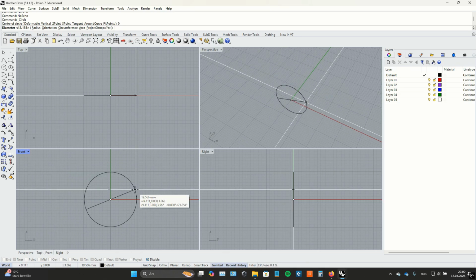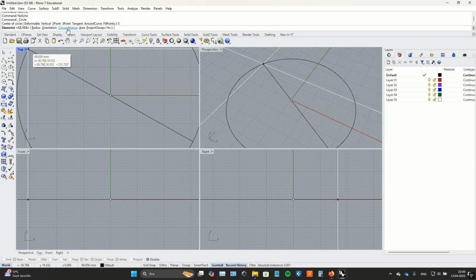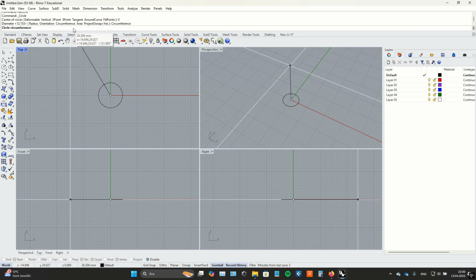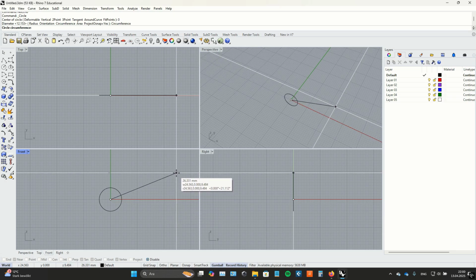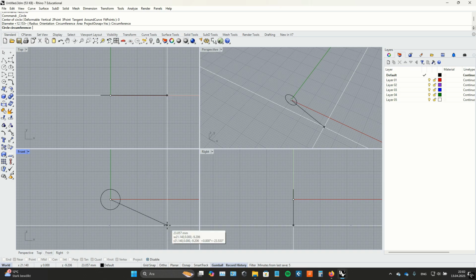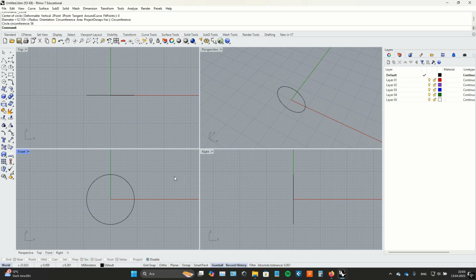I don't click anything just yet, just coming up here and selecting the circumference option so that I can enter a circumference. Circumference is actually the length of the circle that I'm going to be drawing. I click circumference because circumference corresponds to the EU ring size, and I'm going to start with ring size 56. I just type 56 here and hit enter. And now I have my ring rail curve.